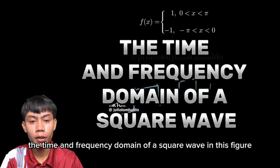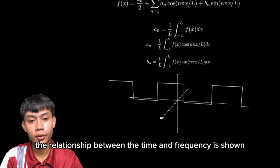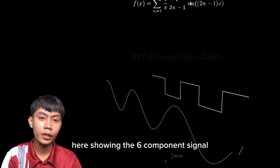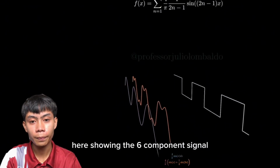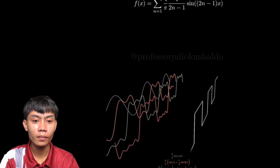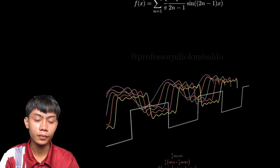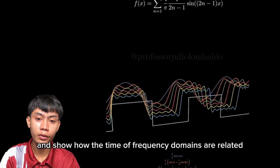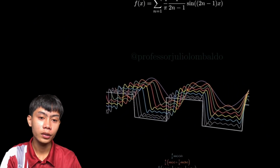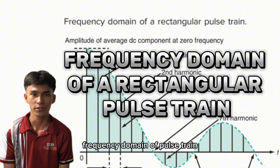The time and frequency domain of the square wave. In this figure, the relationship between the time and frequency domain is shown. Given the time series, we can break down the signal into a weighted sum of sine waves. Here, we show the 6 components of the signal. Each one has 3 features: frequency, amplitude, and phase. Here, we see the amplitude of each component plotted against its frequency, and how the time and frequency domains are related. The square wave discussed earlier is used as the example. The result is a 3-axis dimensional view. Frequency domain of a pulse train.